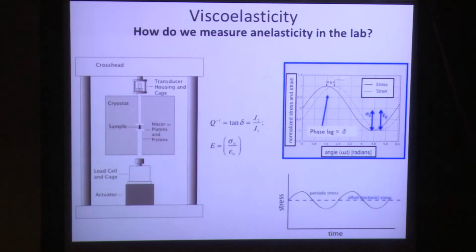I planned to say it earlier, but better late than never, I suppose. When I'm talking about these experiments and what's going on microstructurally, I like to say that if you took a metal coat hanger and bent it back and forth, back and forth, and felt the junction, you would feel heat. What's happening is that you're turning your mechanical energy into heat, into thermal energy. That's happening because defects in the coat hanger are frictionally moving back and forth. It's basically the same idea that we're doing here, and that's why I really focus on the individual defects and the kind of spectra and signal that it gives us.